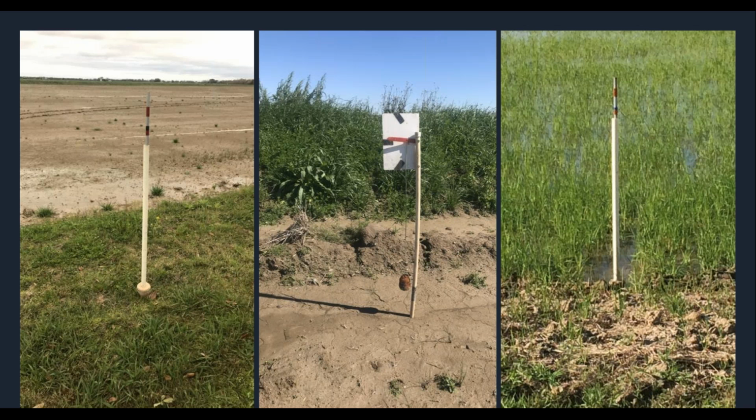I'm now going to change over to after the water hits the field from being pumped from electric-driven wells, where we can actually control the depth of the water using a very practical, very inexpensive device that we developed years ago. And it's very simple. If you look at the water gauge in the middle, it was the one that we had originally designed, and it has a level range of 0 to 4 inches.